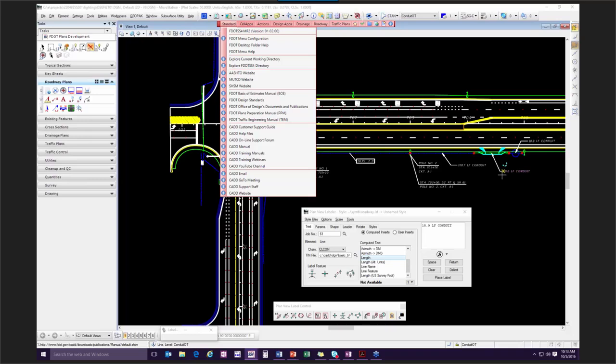But say for lighting, you can have a text LT file that would reference into your plan sheets and place all of your text in there. And when you get into that file, you want to reference everything in and then rotate your view to your clip borders so that when you clip, it is going to be at the right orientation for placing it.